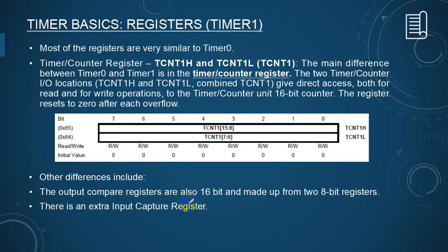What is the function of a stopwatch? When we stop the watch, we want to see how many counts have been made. Same function over here. When your CPU or other activities send a request or interrupt signal to the timer block, it saves the time count in a register.